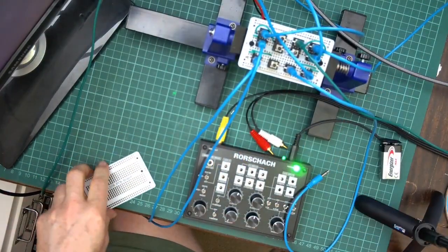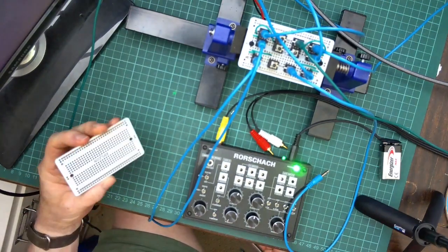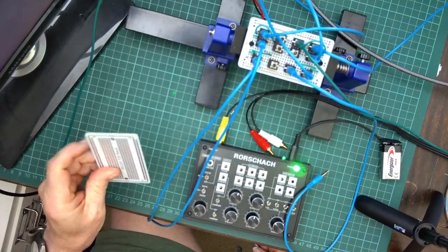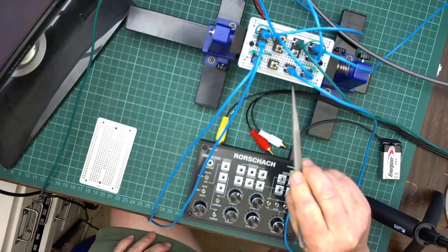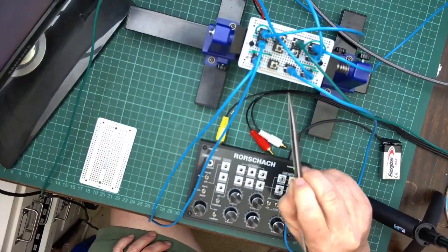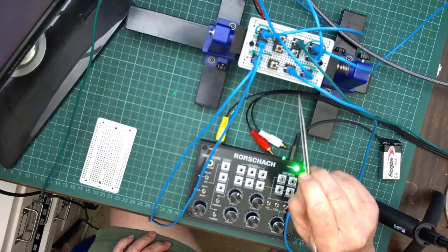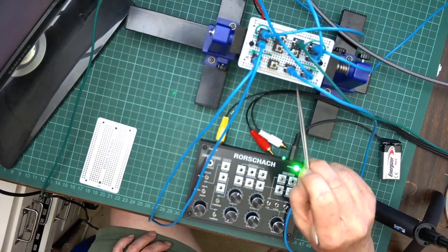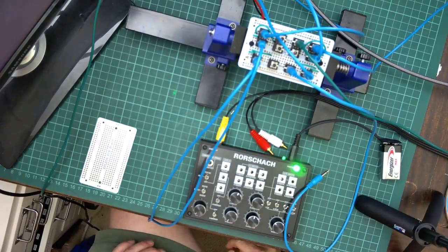Okay, we're back. I put together the circuit. I use these little solderable PCBs here. I just find them very useful for this sort of project. There's 2 layers here. The first layer has all the ins and outs on mini jacks, and then the bottom layer has the power supply, just running off that 12 volt DC, and also the op amp and the associated circuitry. So I've got Rorschach up and running now.